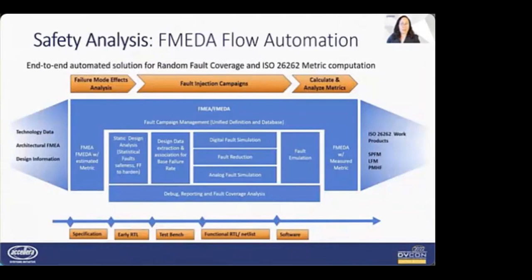The quantitative metric offered by ISO 26262 for measuring design failure rate reduction is the FMEDA, or Failure Mode Effect Diagnostic Analysis. From our perspective, the FMEDA process is not only an after-the-fact analysis of the fault metrics done on the final netlist, but rather a process that begins in the planning phase, helping to set up the technical safety requirements, safety mechanisms, and overall architecture, using estimated design metrics to compute the target ASIL.